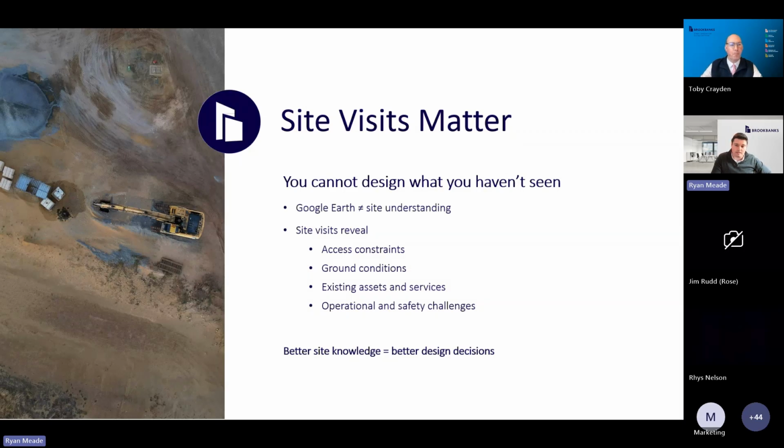Assessing ground conditions, inspecting ditches and existing culverts, making sure that you've got outfalls to ditches where you know where they're going. A big focus of the lead local flood authorities at the moment is ensuring we don't have what they call blind outfalls, where you're draining to a ditch with no known outfall beyond your site. Identifying service locations.